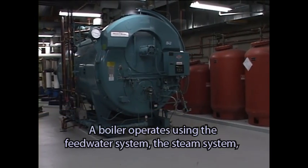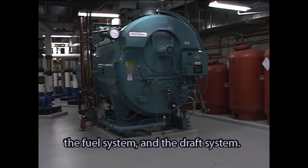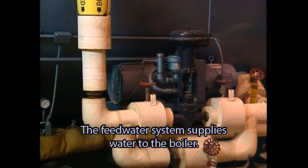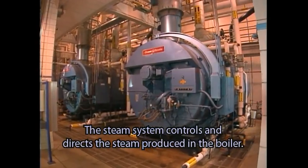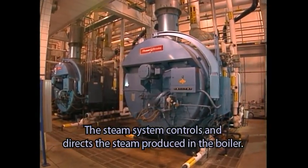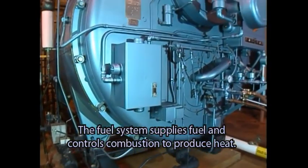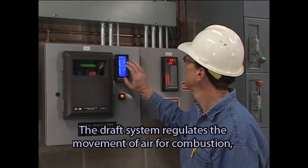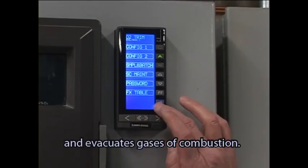A boiler operates using the feed-water system, the steam system, the fuel system, and the draft system. The feed-water system supplies water to the boiler. The steam system controls and directs the steam produced in the boiler. The fuel system supplies fuel and controls combustion to produce heat. The draft system regulates the movement of air for combustion and evacuates gases of combustion.